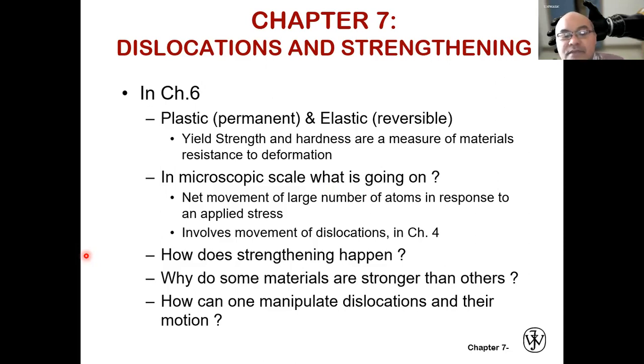We are going also to see why some materials are stronger than other materials, sometimes even though they are of the same type, the same element. Then how can one manipulate dislocations and their motion? By manipulating these dislocations and their motion, the mechanical properties can be adjusted.